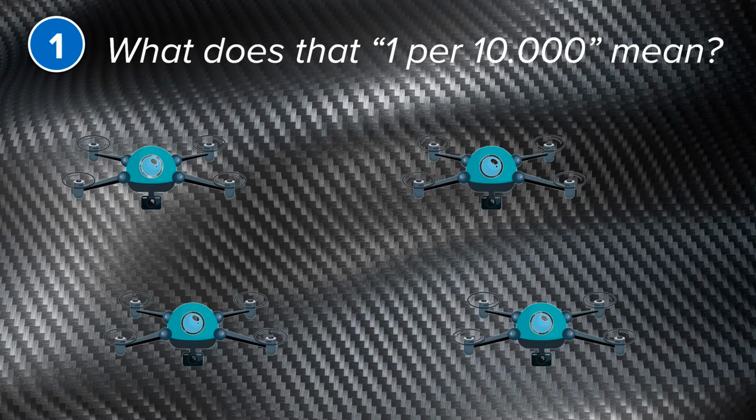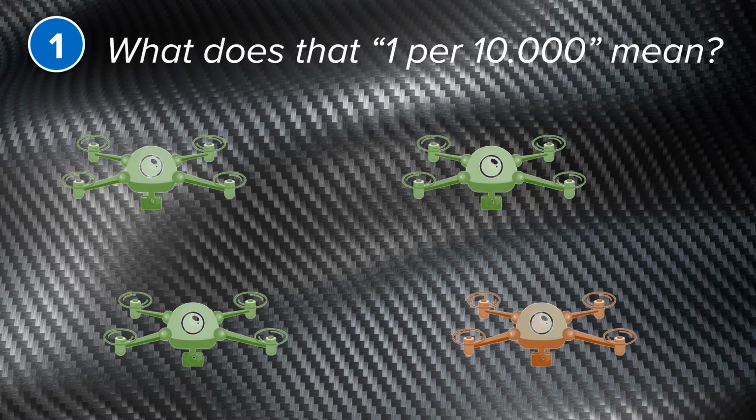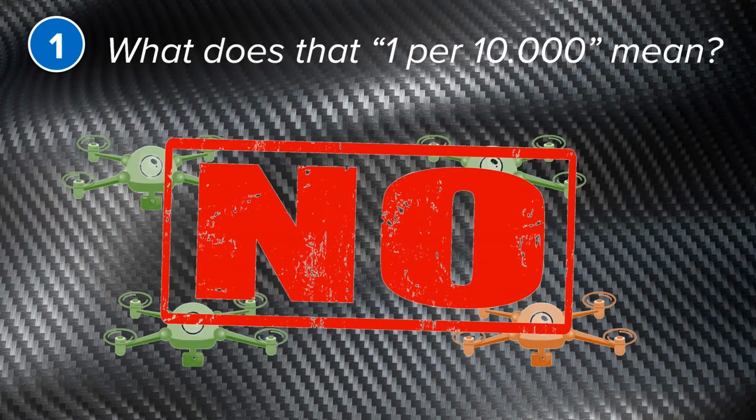And a common question is therefore, if I have 4 really good drones that easily comply with the reliability requirement, but one of them seems to have problems with the compass, is it then possible to use 3 good drones to jointly reduce the probability of a flyaway for all 4 drones? No. The reliability requirement applies to every drone independently, even if we conceptually distribute the 10,000 flight hours on multiple drones. Because this only works if the drones are identical.